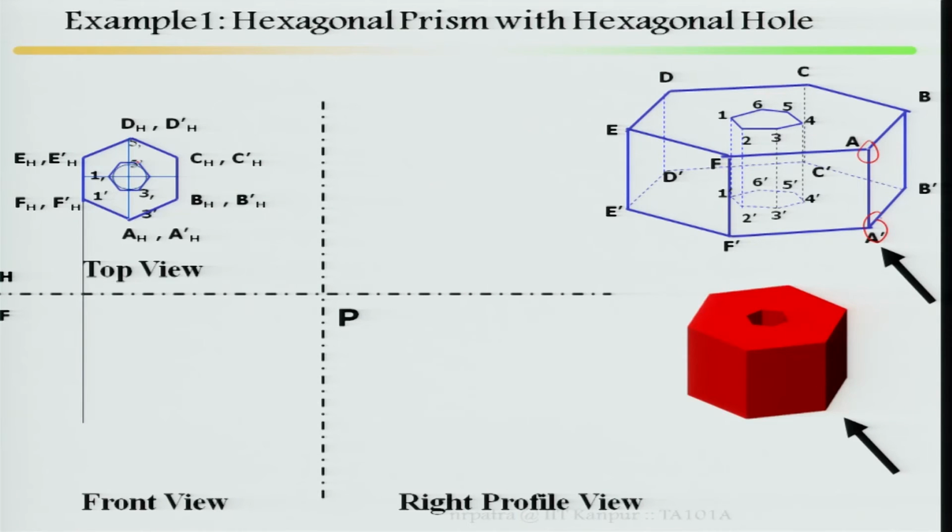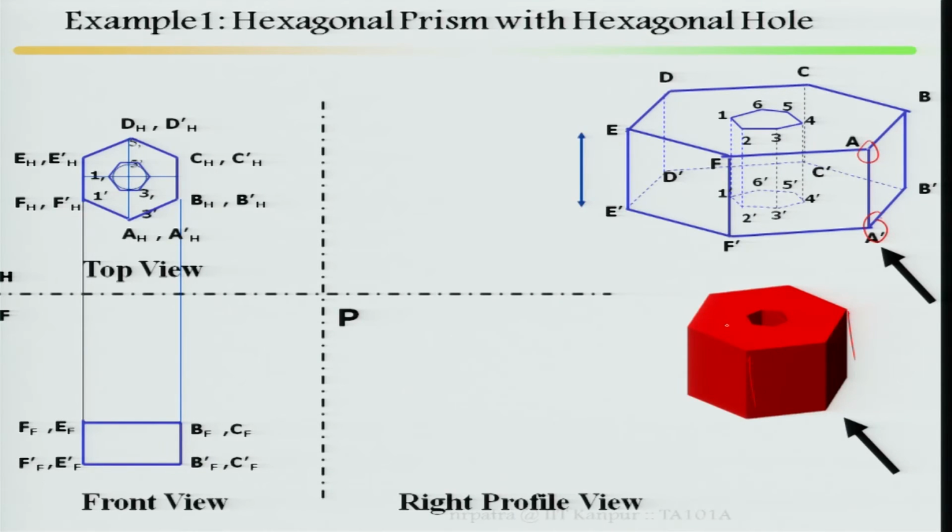Then from there, draw your front view. If I look at there, this is my front view, that means the surface. If I am looking at there, this is my border line, this and this will be merged, but there are hidden lines of your inner hexagonal. Because of that, there are hidden lines. This is a front face, front view. Then mark it front face, front view, front face from where I am looking, from here.